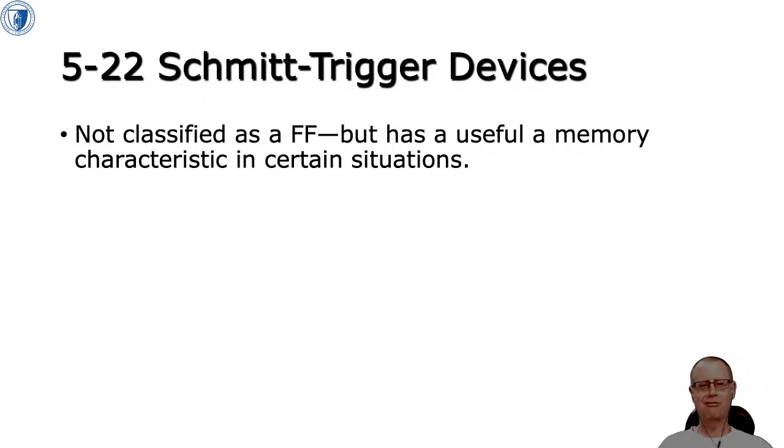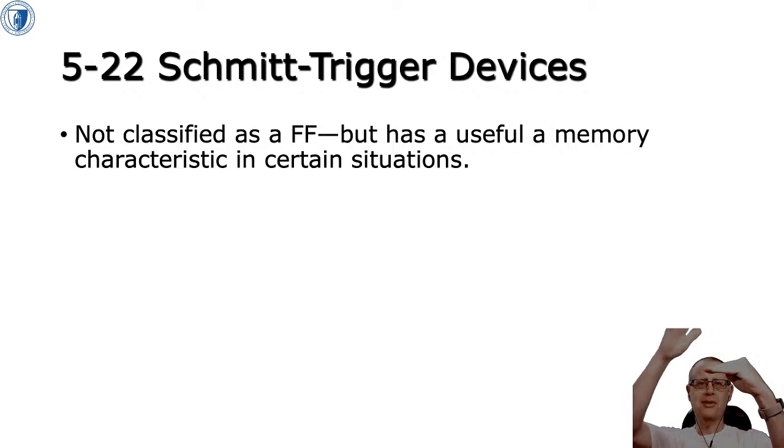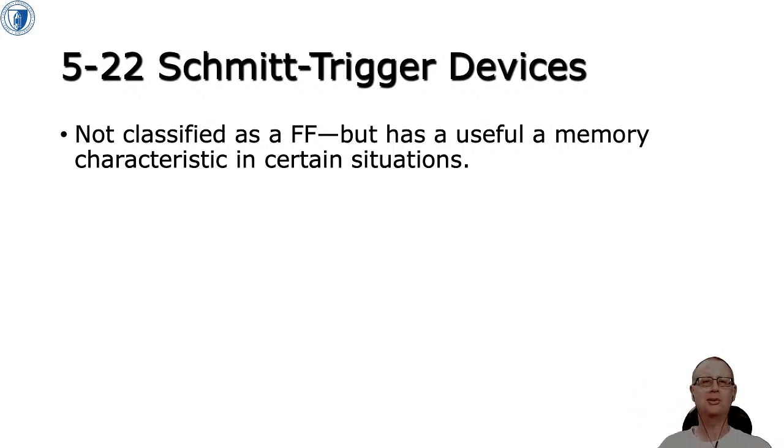So we're talking digital logic, right? Zeros and ones. And the trouble is we've got to represent those zeros and ones using a voltage, right? And the usual way to do it is you put a threshold, and anything above the threshold is a 1, and anything below the threshold is a 0. And the trouble with that is if you get a voltage that goes up and down around that threshold, all of a sudden you get chatter, right? You get the logic 1, logic 0, logic 1, logic 0.